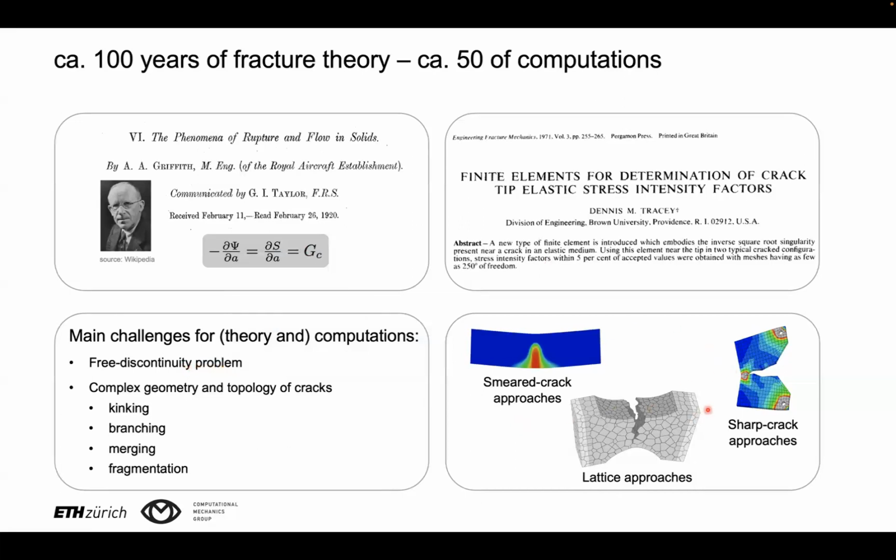Here, without meaning to be exhaustive, I'm just categorizing them simply into three categories: the category of smeared crack approaches, the category of sharp crack approaches, and the category of lattice approaches. So smeared crack approaches are the approaches where we do not have discrete cracks propagating through the specimen. You may be familiar with damage mechanics models in which basically we are solving for a damage field, which you see represented in this example.